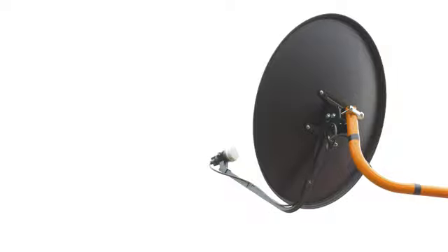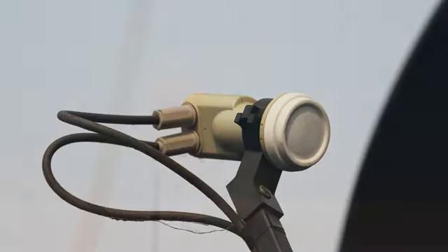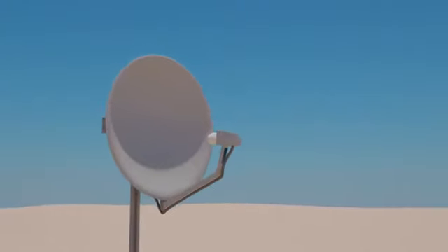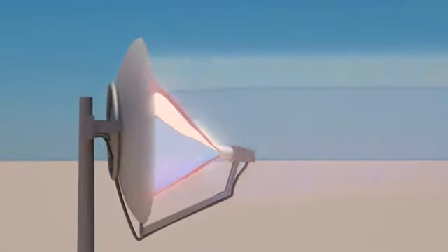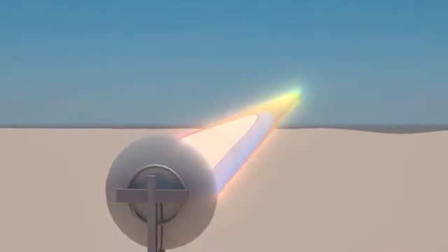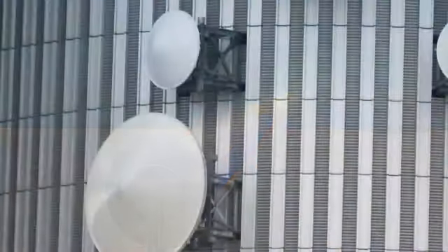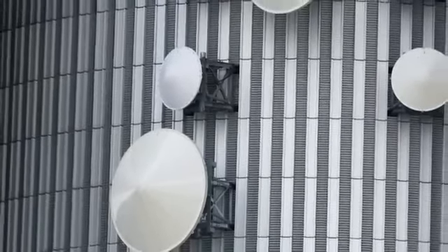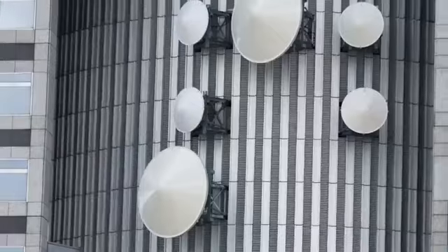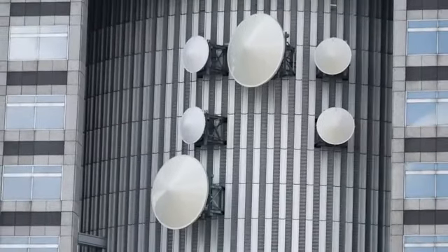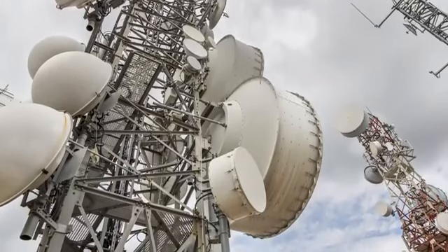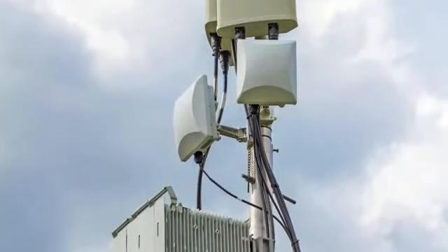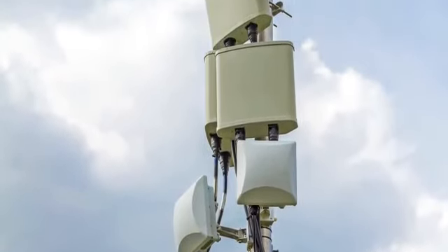A parabolic reflector antenna consists of a parabolic-shaped dish and a feed antenna located in front of the dish. Power radiates from the feed antenna toward the reflector. The reflector concentrates the radiation into a narrow pattern, producing a high-gain beam pointed away from the concave side of the dish. As a result, the parabolic reflector has some of the greatest range of any antenna type. The gain varies with the size of the reflector and the antenna construction, and antenna polarity depends on the feed antenna polarization.